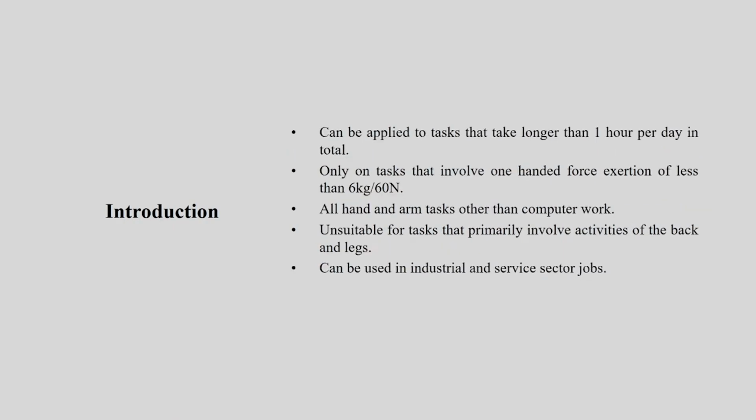This can be applied to a task that takes longer than 1 hour per day in total, and only to tasks that involve one-handed force, with one hand. So, one-handed force exertion of less than 6 kg, or 60 Newton, and all hand and arm tasks other than computer work. Computer work you cannot assess using this tool. It is unsuitable for tasks that primarily involve activities of the back and legs.